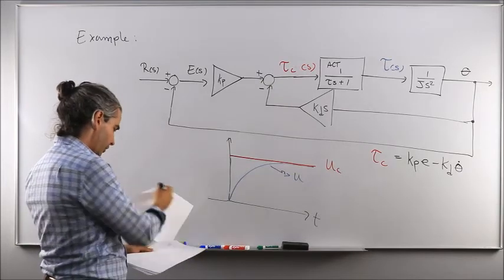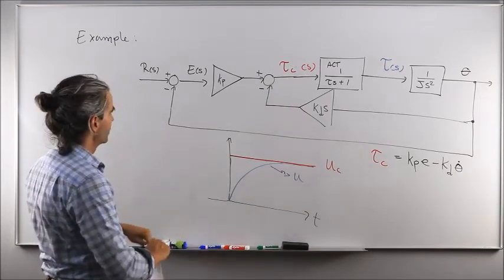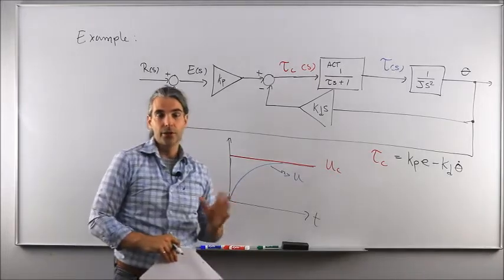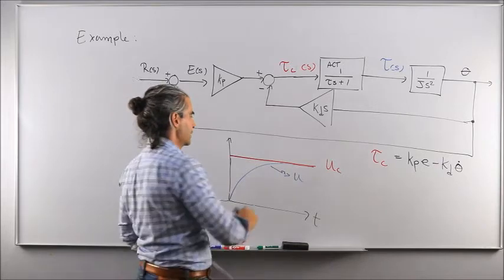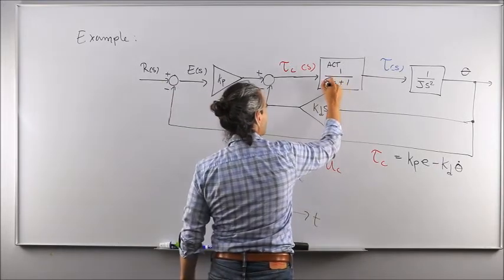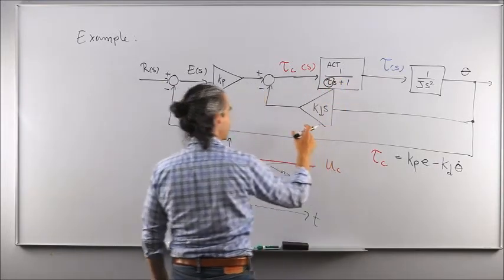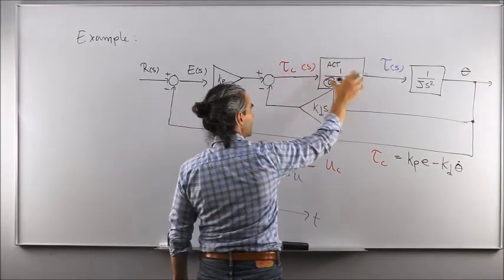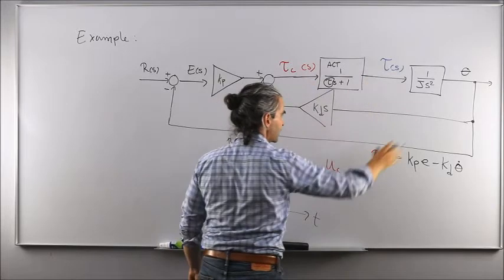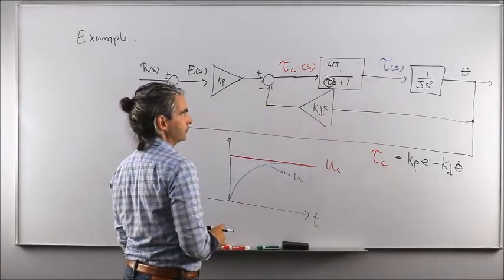So then the trick here is going to be to use the Routh stability criteria to figure out what should be the response time of our actuator, or what should be tau, to ensure that via the introduction of this new transfer function in here, we don't drive the entire system to be unstable. Okay?